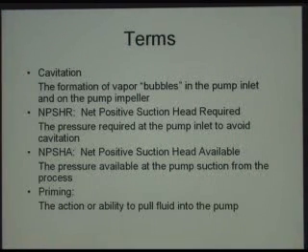If we're going to talk centrifugal pumps, there's a couple of terms that you need to understand and know about, which you may not have been exposed to before. The first is cavitation, and that's the formation of vapor bubbles in the pump inlet and on the impeller. The second one is the NPSHR, the net positive suction head required, and that's the pressure required at the pump inlet to avoid cavitation.